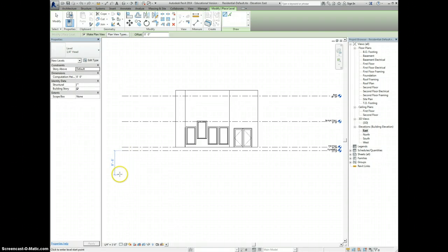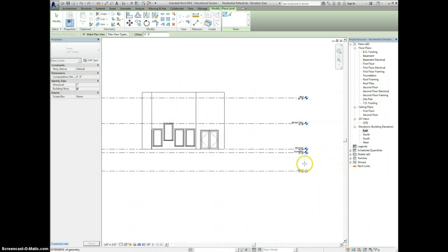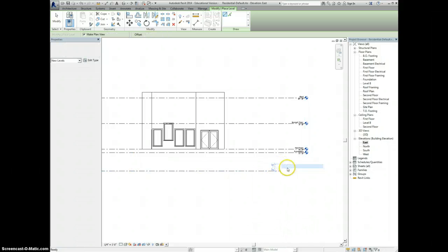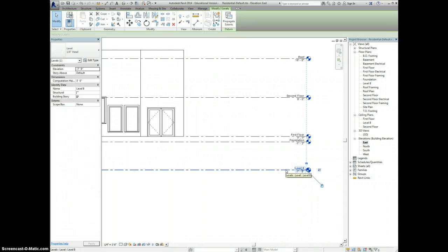Okay, in order to get your lines to line up with anything else, hover over the endpoint, move your mouse straight down, drag it out. Once it's lined up with the other ones, you should get a little blue line saying that it's lined up and locked. If you cancel out a couple of times, you can click on it. You should be able to set how far down it goes. So instead of -7, 9, let's go -9.